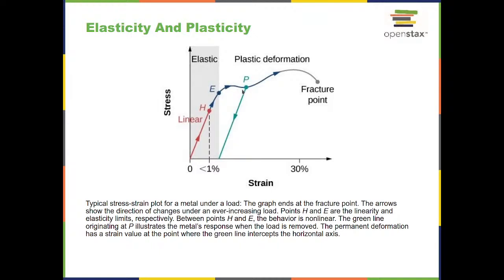And so if we let it deform a little bit and then remove the stress, there's still going to be an elastic slope to this here, but we're going to go back to a different point from where we started. So the object is going to be this much longer even when we remove the stress. If we were to increase the stress even more, then we're going to get plastic deformation.